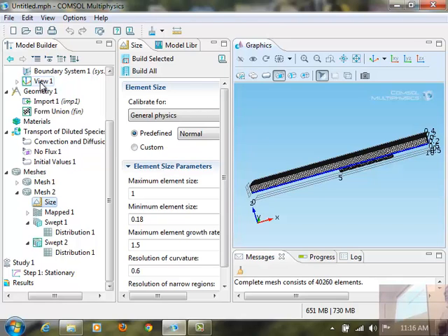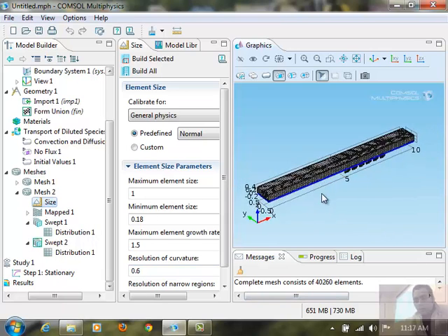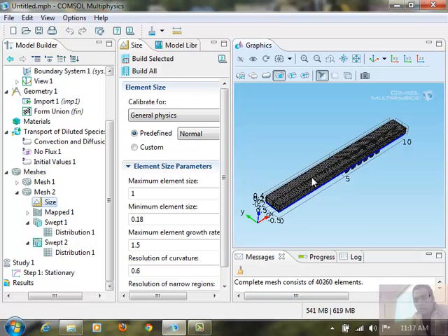Okay. So then you do a sweep mesh. It's just from one plane to another, in both directions. But the other thing to note here is, if you define your top face as a source face and then you want to sweep to the bottom face of this rectangular domain, you cannot do it because it doesn't conform. You have only two edges. The general rule here is your source face can have multiple faces, but your destination face for each domain should have one face. That's what they say in their manual also.